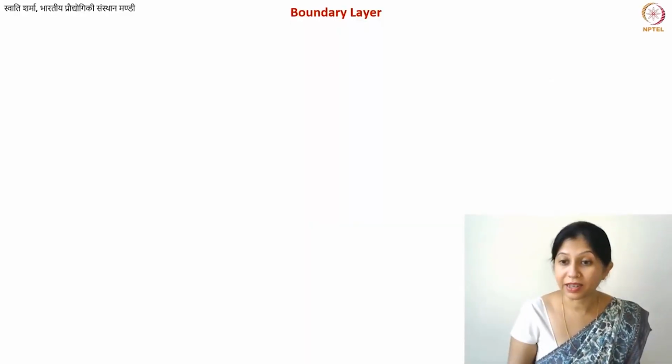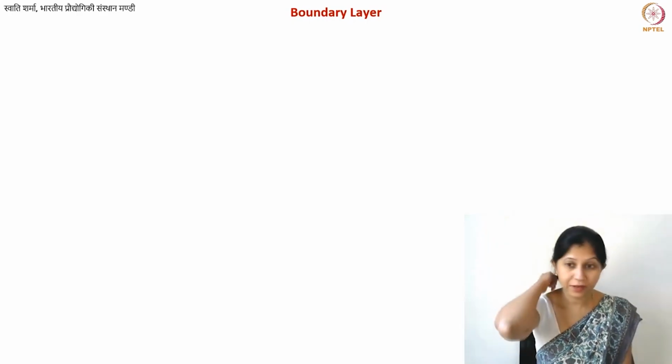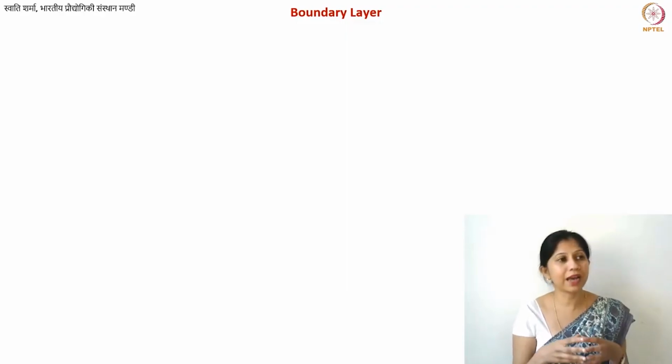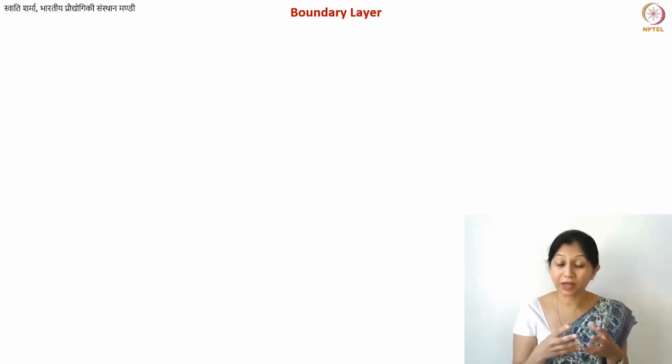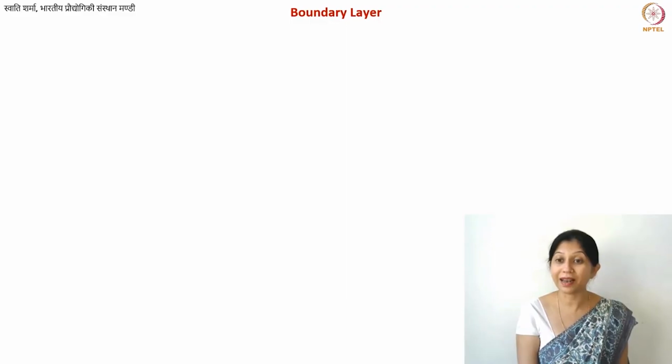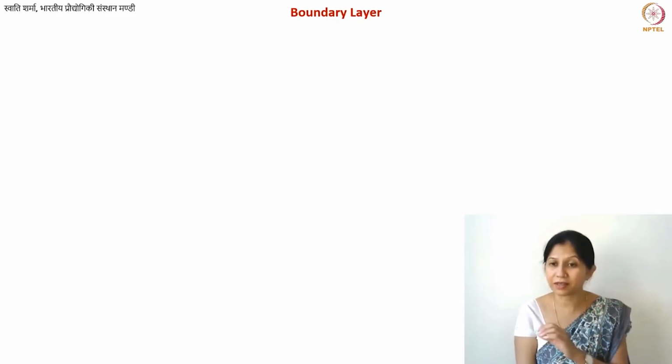This is our second lecture on the chemical vapor deposition of graphene. So what did we learn in the previous class? Briefly, we learned that, number one, there can be different types of CVD reactors. Some of them have the entire CVD chamber heated and some of them have only the substrate heated. Also, the flow inside your CVD chamber must always be laminar. And we also learned that there are various parameters that influence the CVD reaction. That basically means that they influence the deposition patterns or the quality of your deposited films.